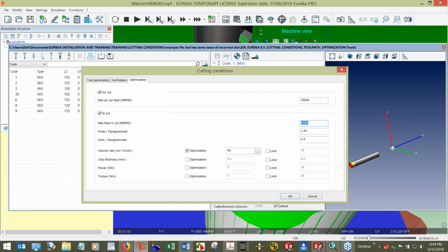So I said, well, okay, let's assume that the feed rate they had, the 2,500, was about 80% of the cutting data. Because when we go look in the book, they give you a range on the tools of what you can feed it. So I said, well, let's be conservative. They publish all the formulas, and they're straight machining formulas. And they give you a range.